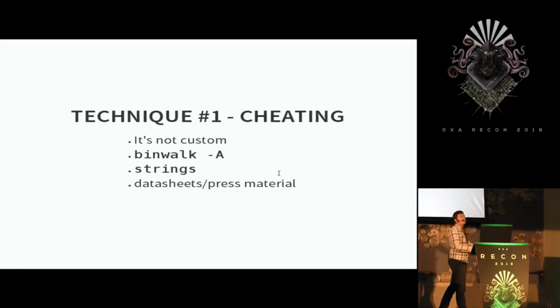They support adding custom instructions as well, but they're based around a common core that, Hex-Rays has a disassembler for some of it, I believe. There's definitely disassemblers out there for some of those, and those serve as a starting point for 99% of what you'll need. And of course, you have your friends binwalk -A, which can sometimes identify an architecture for you if you're lucky. Strings is great, datasheet, press material. Don't neglect this stuff before you dive right into the fun technical work.